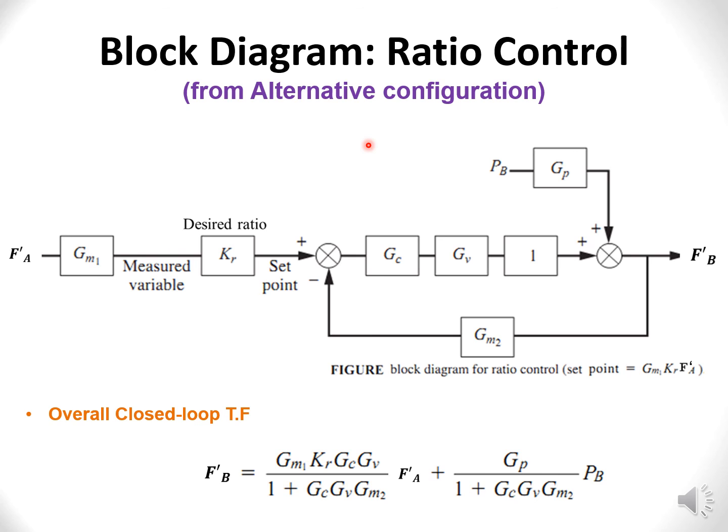We'll never get an optimum controller that way. We have to be sure that when we use it for set point change, and when this same tuning is used for disturbance, it is going to be good enough to give us the result, to reject the disturbance or give the set point that we want.